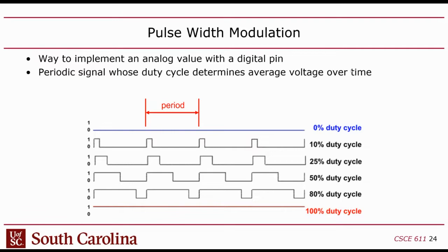And as a result, when you design the chip, you have to isolate analog circuits from digital circuits because the digital circuits are noisy. They cause noise from their shifting from 0 to 1 transitions and 1 to 0. They put noise on the power supply, they put noise in the substrate, and then they put crosstalk noise. So you have to be careful how you design analog circuits in a mixed signal chip. So ideally, we wouldn't have those.